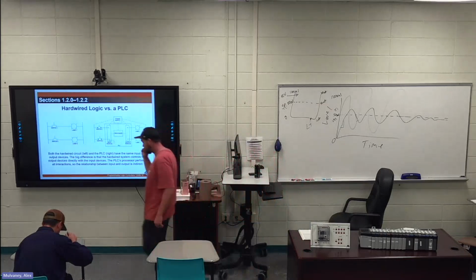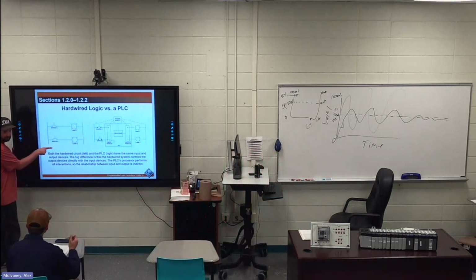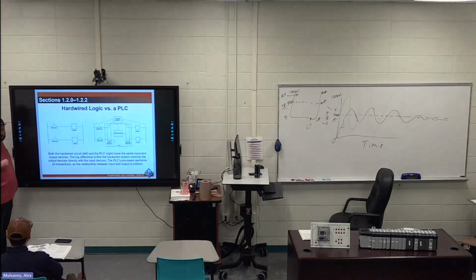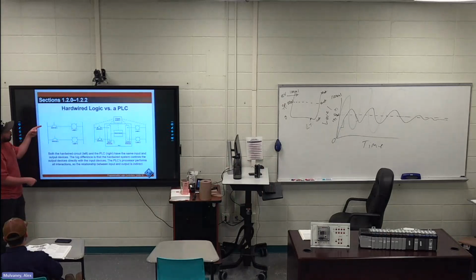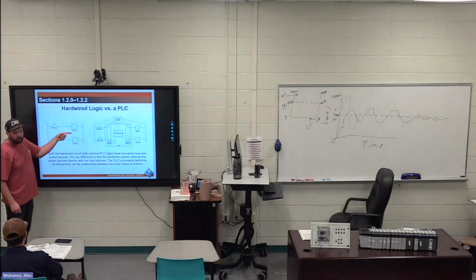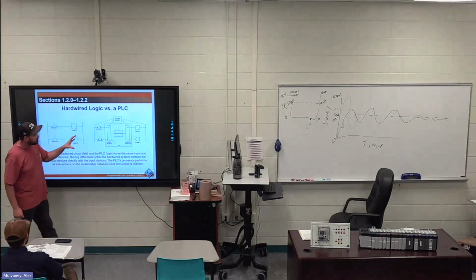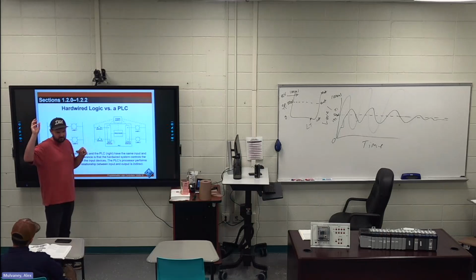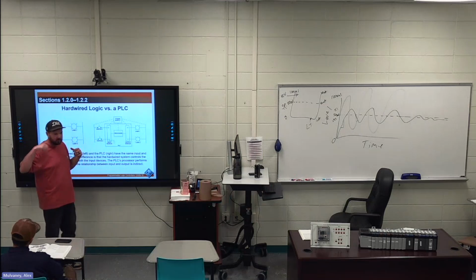All that's saying is everybody has wired up this circuit over on the motor trainer, right? This is like circuit number one. This is hardwired stuff. This is being controlled directly. This is our power coming in. It's trying to get over there. I push that, it's a push button, not a switch, the lamp comes on, and it's directly connected, right? This is directly connected to this. All this is saying is that with the light connected to my PLC, when I switch that on, I'm not turning the light on. I'm telling the PLC that switch is turned on. That switch is dumb to the fact that it turns on a light. Does that make sense? It's just a switch, that's all it is, right?